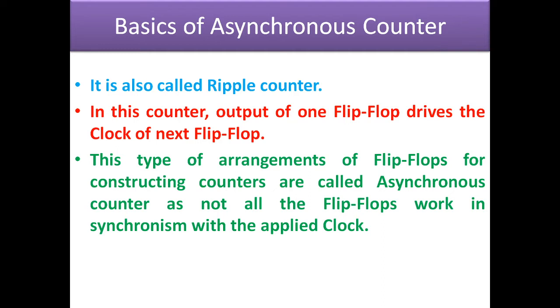The clock is applied to the least significant flip-flop, and the output of that flip-flop drives the next flip-flop, and the next flip-flop's output drives the next flip-flop. In this order, the information is passed on from one flip-flop to another. Hence, we call it a ripple counter.